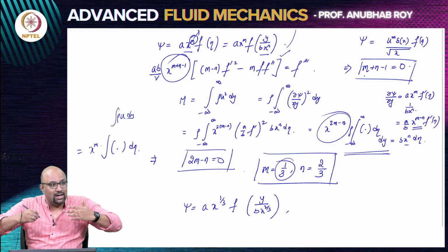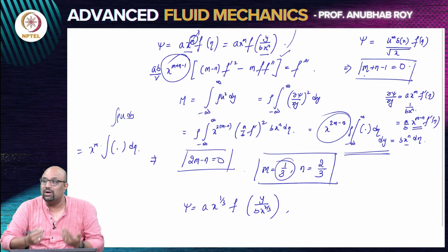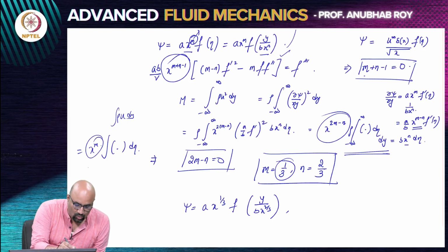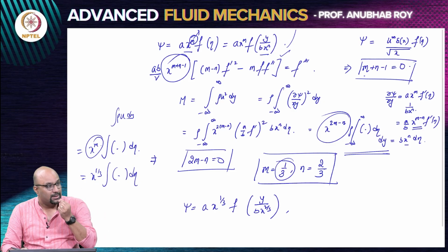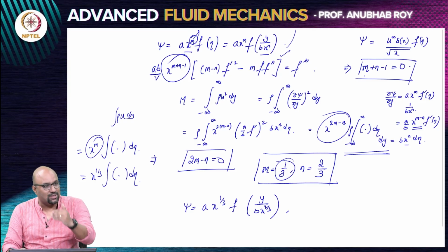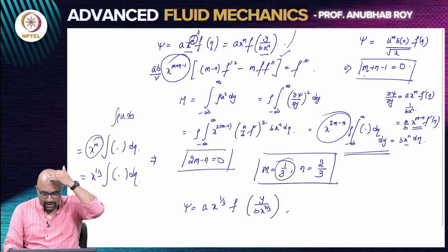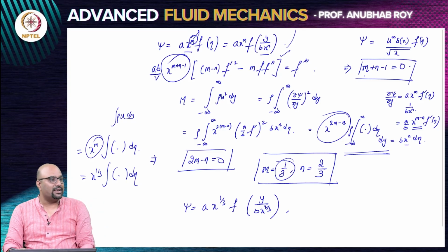So automatically the amount I have to carry out is going to be larger than what I brought in. Which is why this quantity is going to continuously keep growing. As you keep going further and further, the mass flux at different x locations, where you have taken a slice at a given x location, is basically increasing.